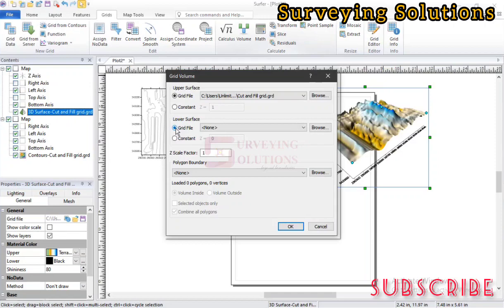However, instead of choosing another grid file for our lower surface, we are going to use a constant, which will now serve as the lower surface. That means the next surface for this particular grid volume will be 28. We told you in the beginning why we have 28. By design we chose 28 as the elevation of that terrain, and we want to cut those values that are above 28 and fill up those values that are below 28, respectively, right? Good.